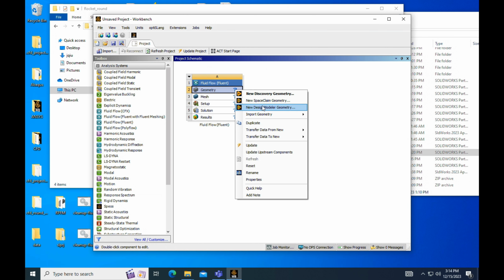And we will begin setting up, or we'll update our mesh, and we'll begin setting up for the simulation. We're going to make sure double precision is on for processors to make it quicker, and we will save. And when that loads up, I skipped ahead, it takes quite a little bit. We're going to press OK.